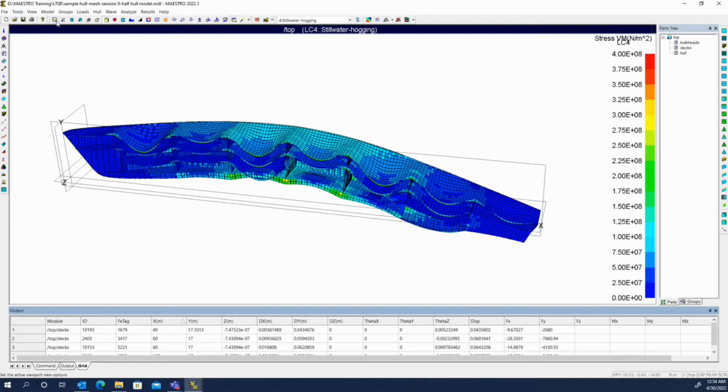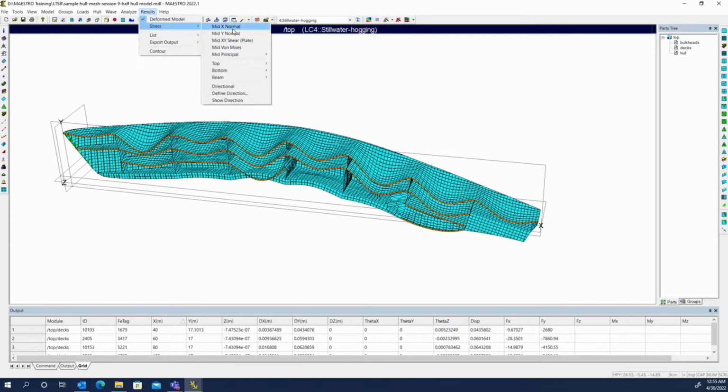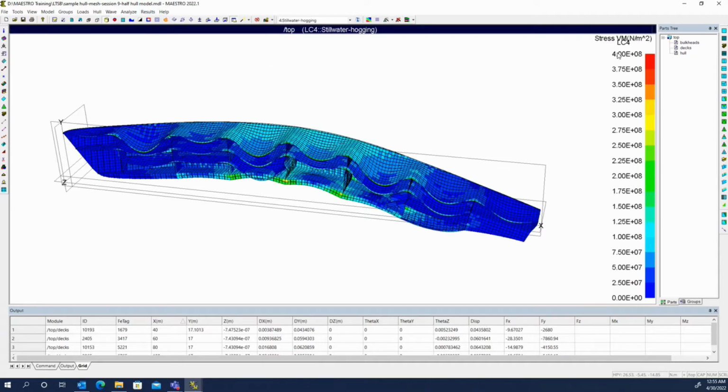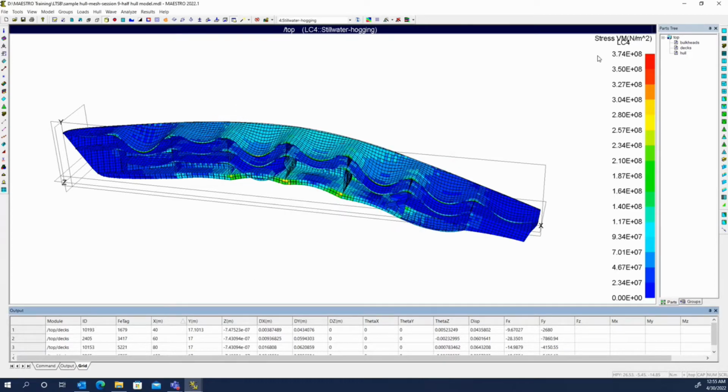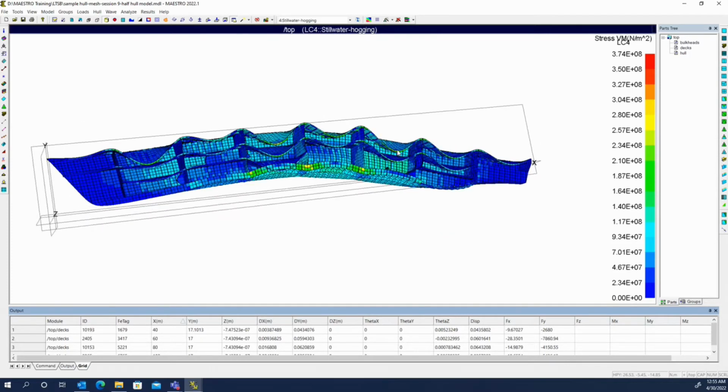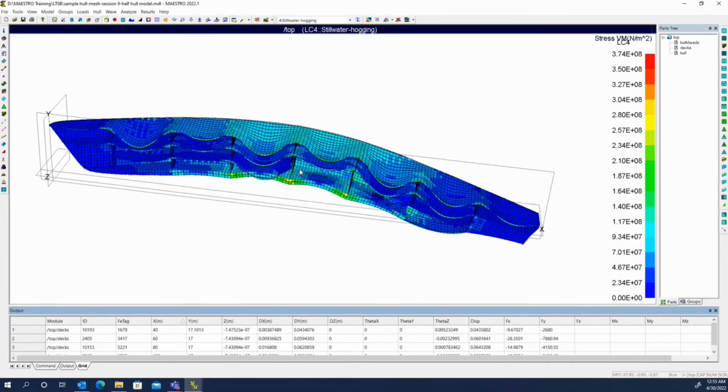Although if you don't manually specify the plot, if we switch to element type and then we replot the stress, oh, it did remember. I thought it was going to move the auto ranging. If we turn that off, it'll switch back. And this is a quick and easy way of finding the highest stress in the model. Now, it might be one tiny small tri in an odd place. It's not necessarily a large portion of the model. It's one single extreme element somewhere in that model.